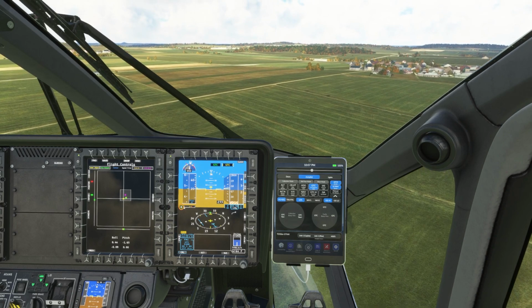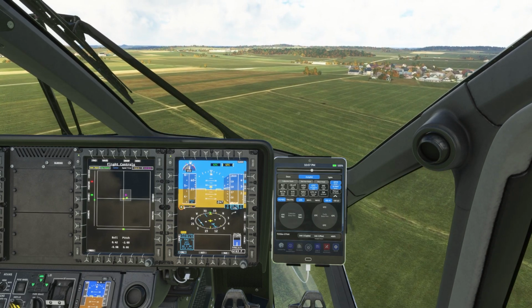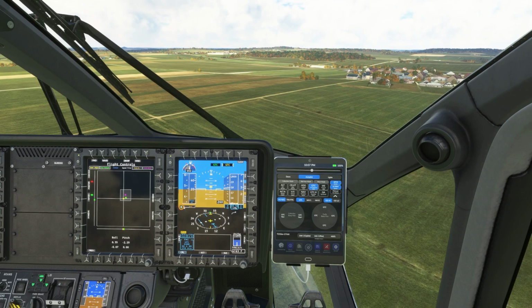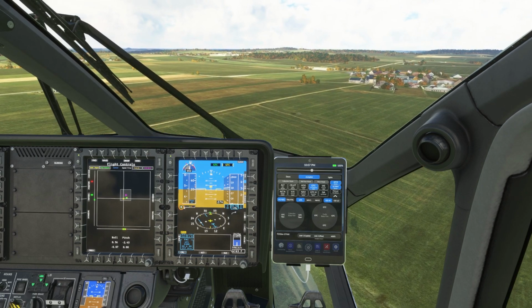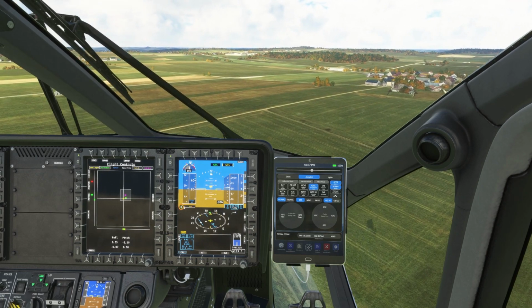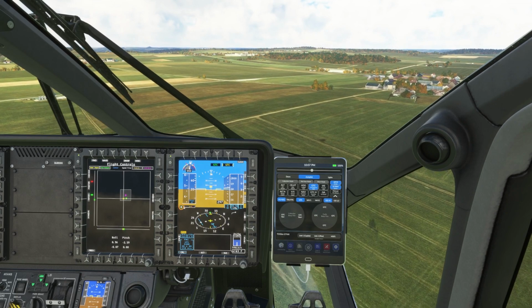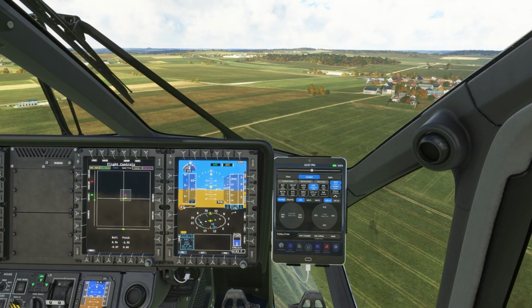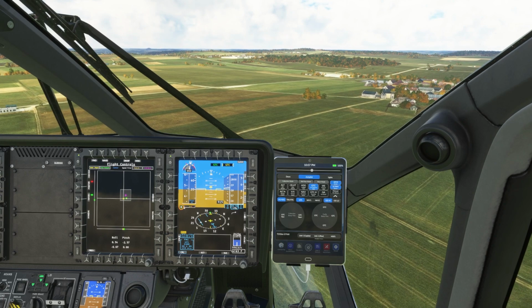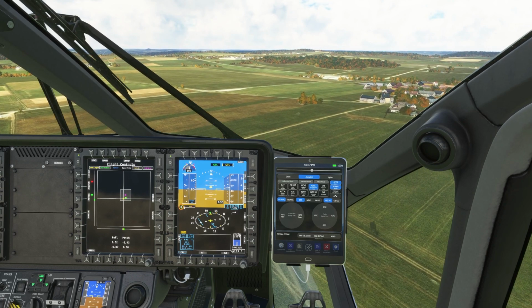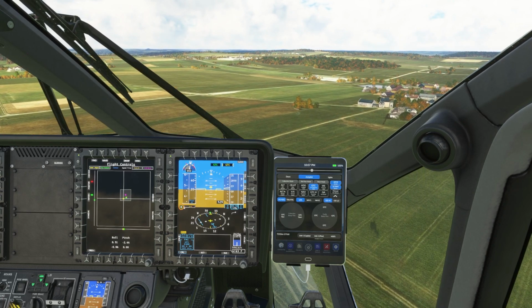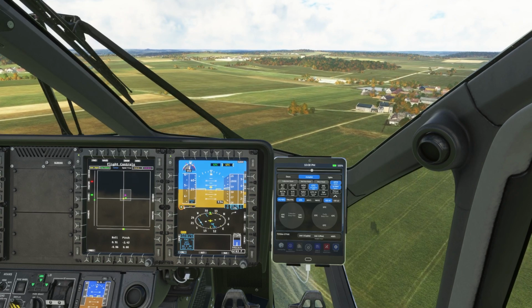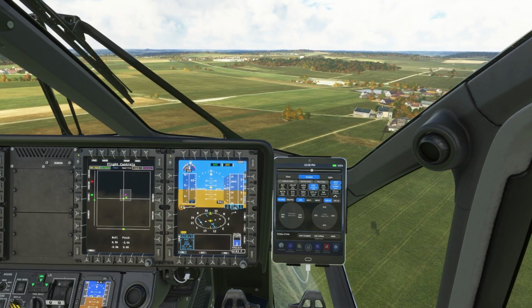And GTC on the collective beep trim, you've got your yaw here. Pressing that is going to actually yaw the helicopter a little bit more. So you can set yourself up in a nice matched speed situation with a moving ship as you come in and prepare to do your landing. That's what the ground speed hold mode would do.